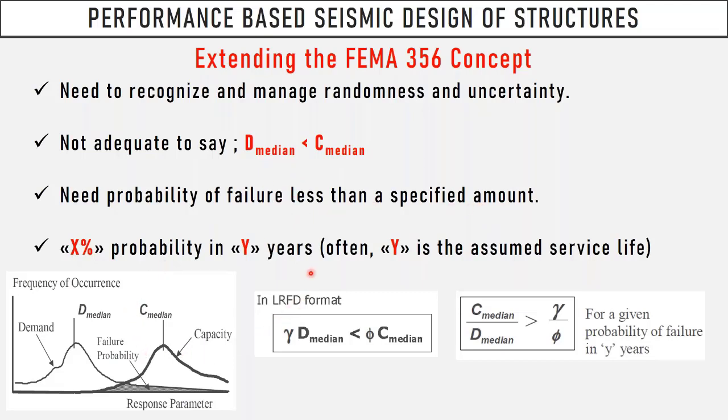And in the LRFD approach, what we do, we increase the demand and we decrease the capacity and try to find a kind of probability for a given failure in certain years. Most of the times it is the service life. But don't forget, everything that we are dealing with has a distribution.